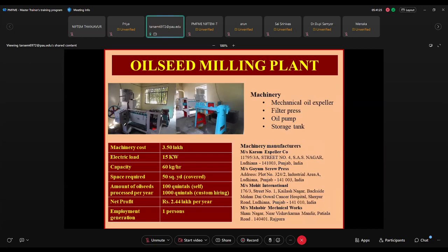So when we extract the oil from the oil expeller, we have to put the oil seed meal in again and again, about 3-4 times, to get the maximum quantity of oil, so that the oil in the oil seed meal remains below 5%. And then that oil may contain some unwanted material, which has to be removed. So we keep that oil for 24 to 48 hours in the settling chambers, where due to sedimentation heavy impurities are separated out.